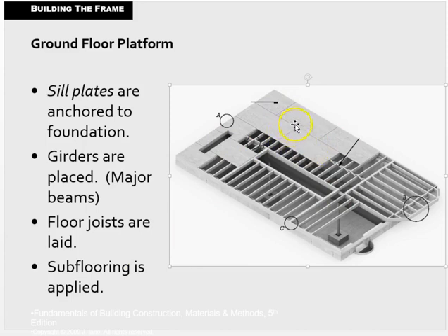And typically the subfloor is applied perpendicular to the joists. It's almost always. I can't think that it would ever not be when it comes to the subfloor, but as we'll see in some images moving forward, sometimes wall sheathing will be installed not perpendicular. But putting it in this fashion gives you the most rigidity. This is the best way to do it. The long joists are running in the short direction of the sheathing or drywall that pertains to as well.